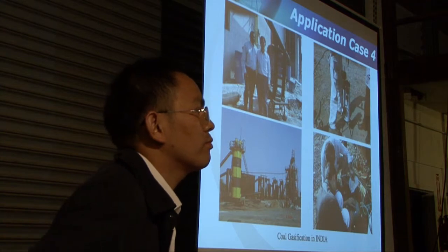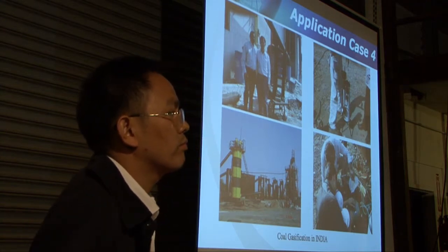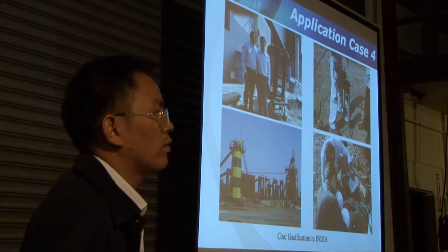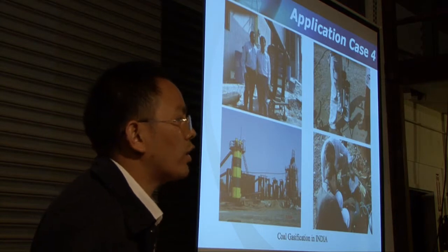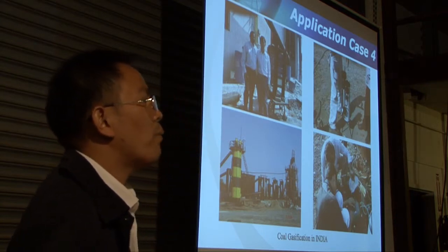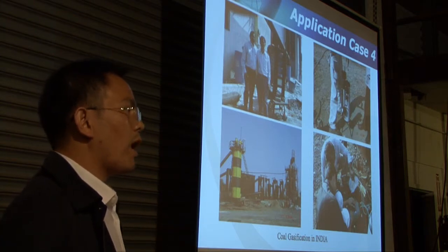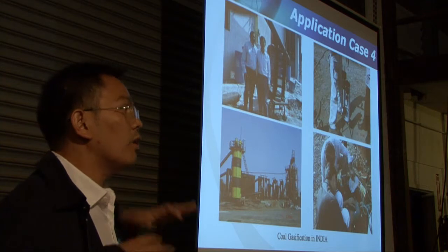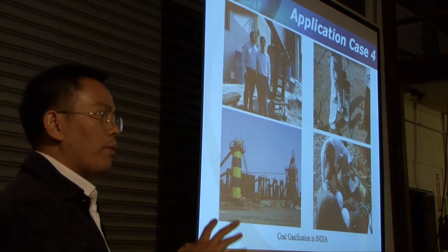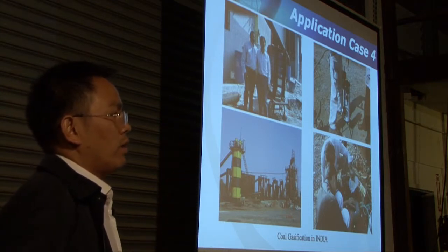What is the maximum oxygen that they felt was safe in the electrostatic precipitator before they could have a combustion event? What is the highest level of oxygen that they wanted to see? 1%. Yeah, in China, if more than 1%, the ESP should be closed. No electricity. If more than that, a problem. 1% is very important.